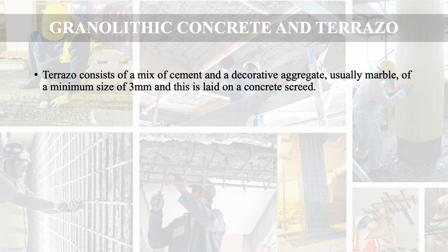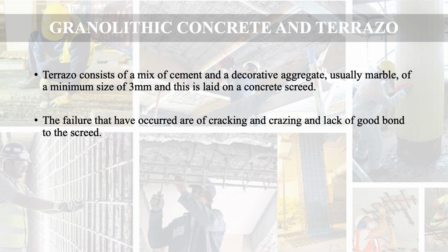Terrazzo consists of a mix of cement and a decorative aggregate, usually marble. If we talk about the size, then the minimum size is 3 mm, and this is laid on a concrete screed. The failures that have occurred in such types of floors are cracking and crazing and also lack of good bond to the screed. These are the three problems: cracking, crazing and lack of good bond to the screed.